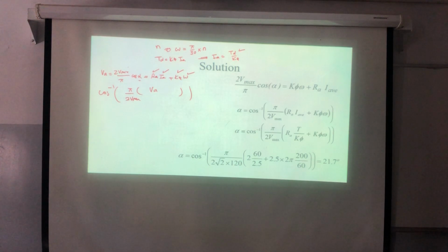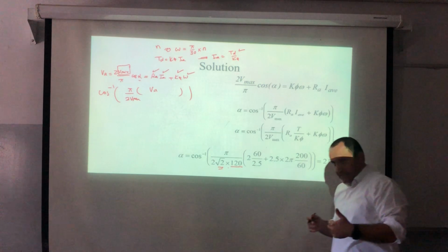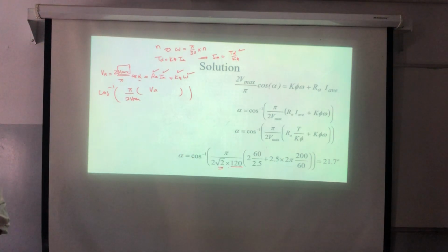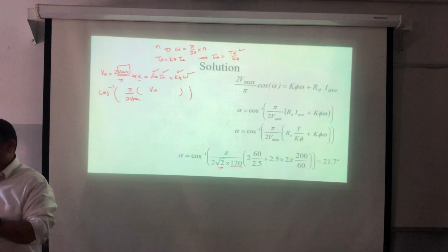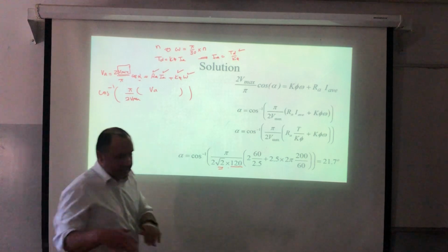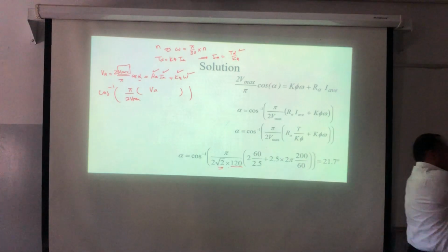This one here is the maximum value. What's given in general is the RMS value, so you should multiply it by square root of 2. So in general, if we give a supply, unless I'm telling you something else, it will be the RMS value: the RMS value for the single phase, and line to line RMS value for the three phase. Good? Unless I'm telling you something else.